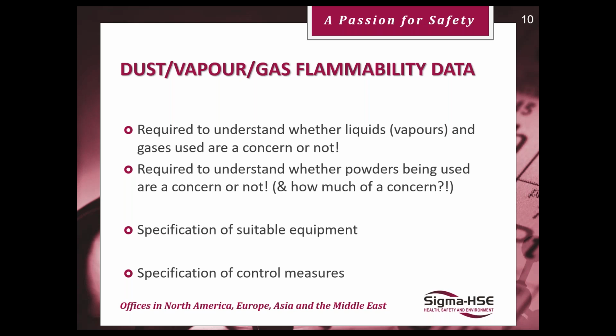And we can do that by trying to prevent the flammable atmosphere, that fuel-air mixture, for example by inerting the system, removal of the oxygen, or working at low temperatures, or working under vacuum. If we can't avoid our flammable atmosphere, then we specify equipment which has a much lower probability of acting as a potential ignition source.